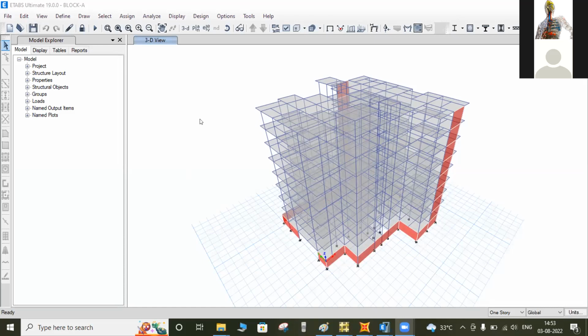When we complete the first analysis, we move to external loads, as external forces. What is the behavior, or the response of the structure, when we apply the external forces? The forces are distributed in two parts, gravity and lateral. For gravity loads, we need to calculate which force we take. If we use the Indian standards, we calculate the gravity loads like frame loads, area loads, point loads, which depend upon the finishing of the material as per the architects' requirement. So we are calculating all the frame loads.